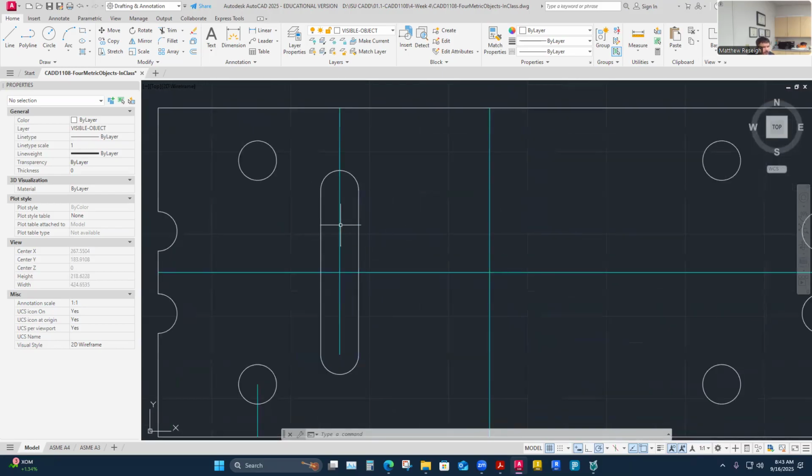So now I think I'm just going to array that 6 times. So we've done a polar array. We'll do a rectangular array on that. My array command has those options that we explored last week. I'll choose the rectangular version and it wants to know what I'm going to array. I'm going to array this thing. And then I just hit enter or right click.